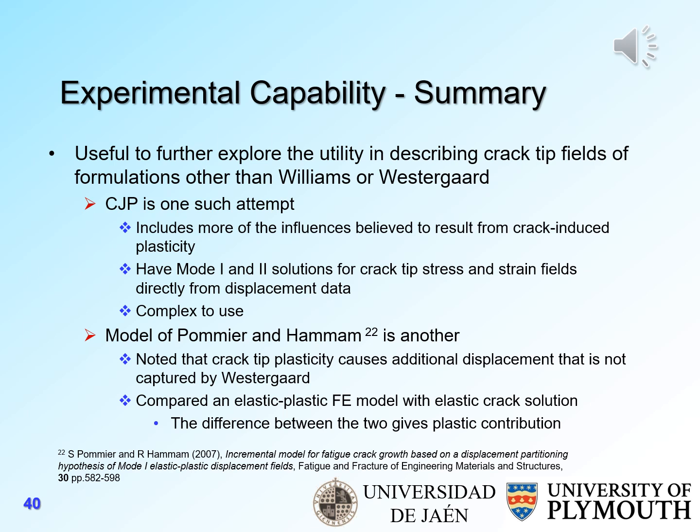They noted that crack tip plasticity causes additional displacements that is not captured by Westergaard. And to get a value for that additional plasticity, they compared an elastic plastic FE model with the elastic crack solution, with the difference between the two giving the plastic contribution. And some work by Knoll has examined the model of Pommier and Hamin and the CJP model and concluded that they both are dealing with the same issues, although in different ways. But there is significant scope for further work on both those two models, their differences, and indeed on other models.